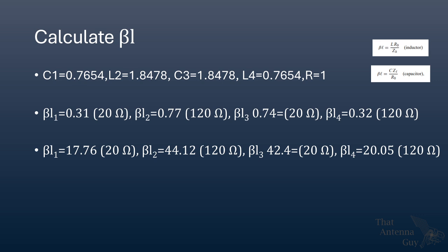So once you get these values, you can go ahead and plug them into something like LineCalc, where you give it the characteristics of the substrate you're using. You use the impedance to figure out how wide that line should be, and then you use the beta L to figure out how long that line should be. And when you plug those all together and feed them in with your characteristic, in this case 50 ohm lines on either end, you'll get a functional low pass filter.